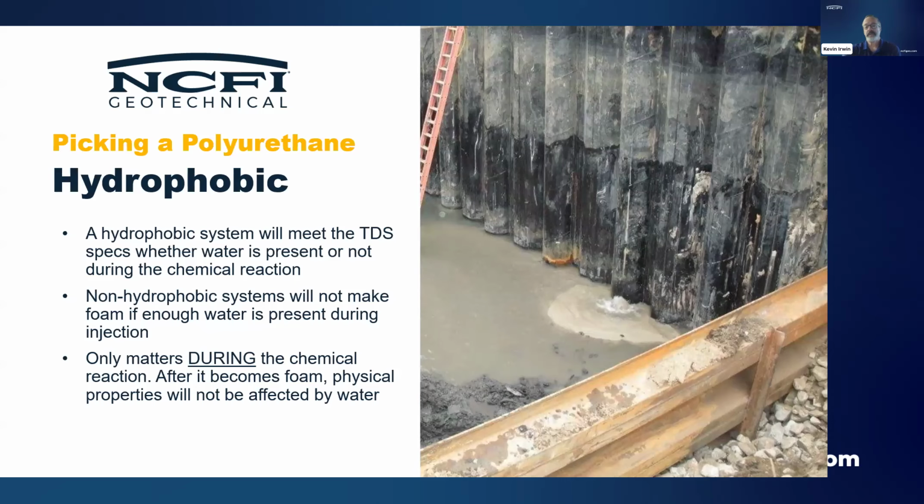And hydrophobicity. So a hydrophobic system will meet the TDS specification whether I shoot it directly into water or not. I'm sure some of you on the call have been around when a non-hydrophobic foam was injected into water, and it doesn't turn into foam. It's certainly not solid, let's put it that way. It tends to string out, get really gooey, and there's no structure to it. So non-hydrophobic foams are not going to make foam if you pump it into water. A hydrophobic system will, and should still meet the technical data sheet specs.